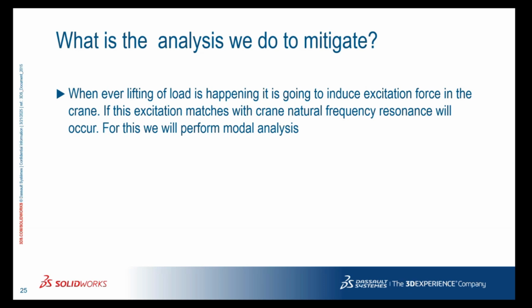Maybe some other vibrating objects will also be there within our work area. If those vibrations match the natural frequency of the jib crane, it leads to a disastrous problem in our work area. So with that aspect, we have to consider first natural frequency resonance also.